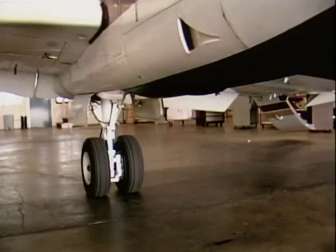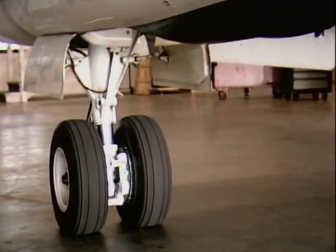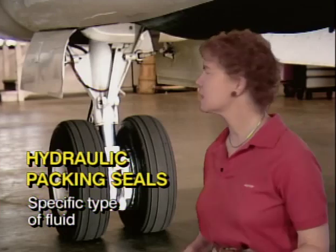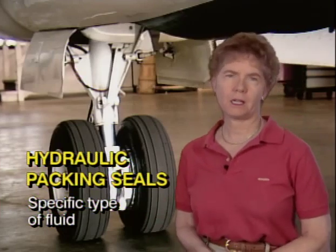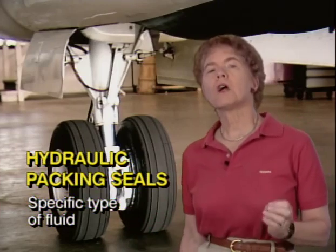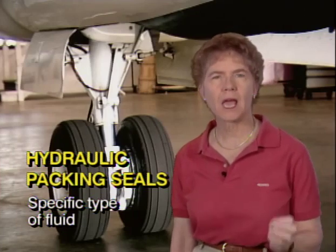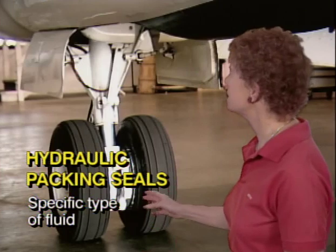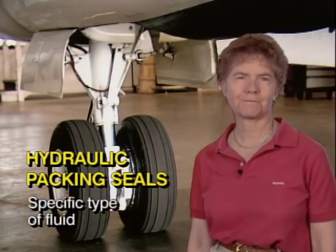Now, on a landing gear shock strut, the hydraulic packing seals in it can be used only with a specific type of fluid. Whether they're natural or synthetic packing seals, you can't just mix and match on the fluids. You've got to make sure that the hydraulic packing seals that you use are compatible with the specific type of fluid required by the manufacturer.